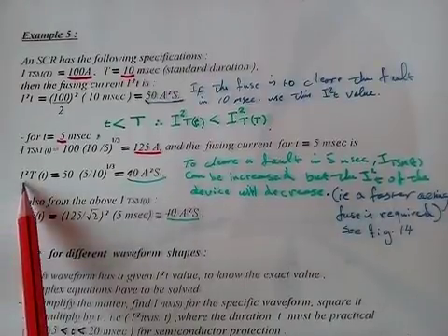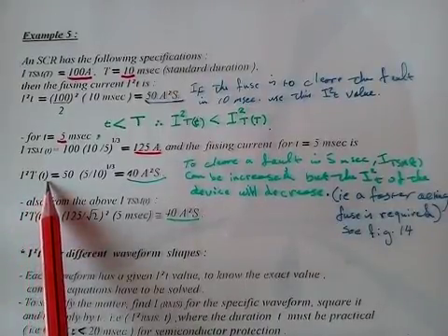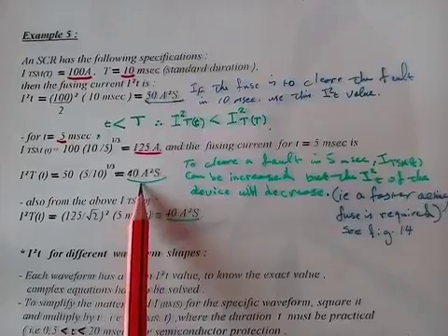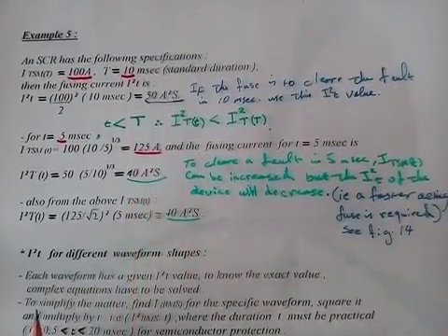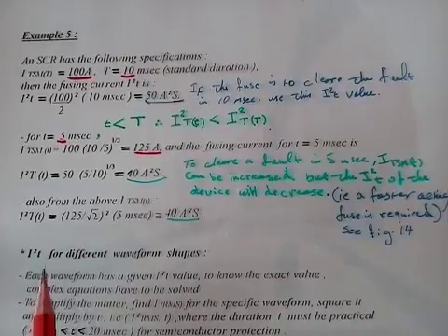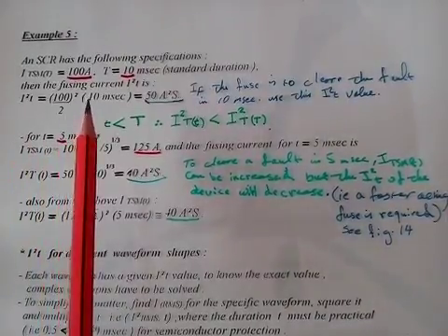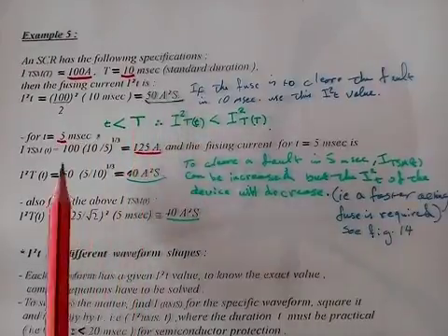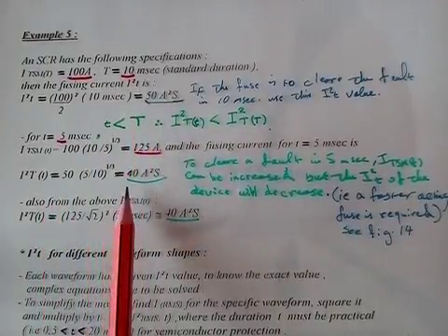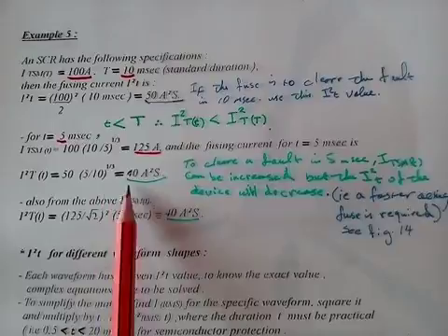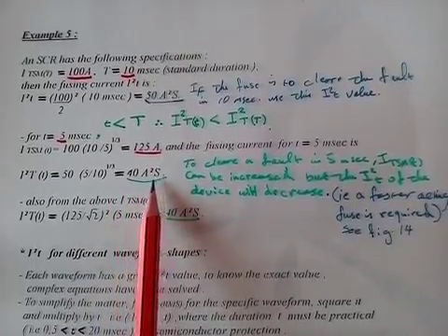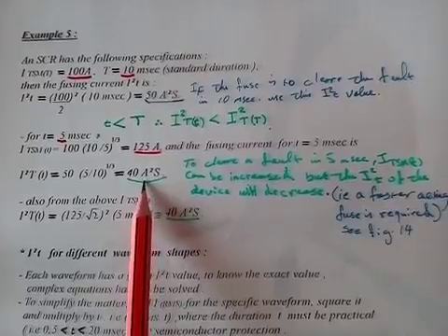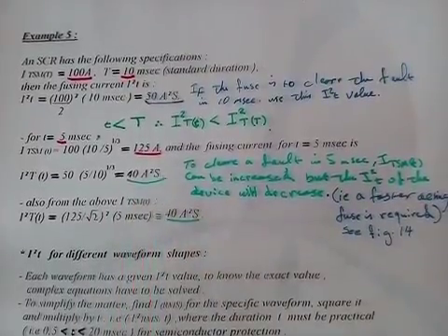And the I2t for the whole device would become 40 amps squared second. So when you clear it at 10 milliseconds, it's 50 amps squared second. Because you stress that device more by increasing the surge current, it becomes only 40 amps squared second. And that means, of course, a smaller fuse to protect that device.